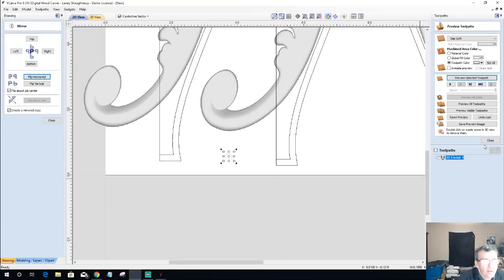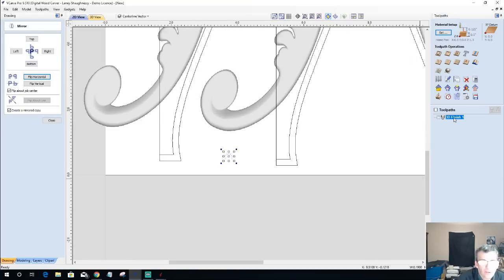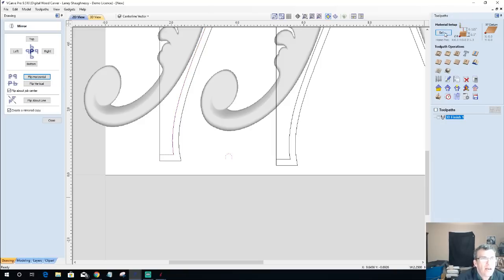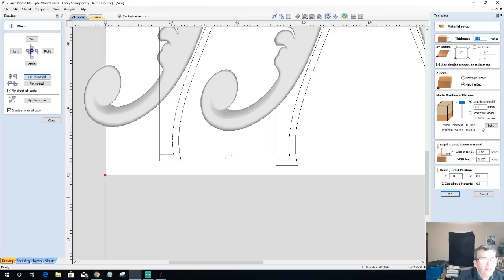And we should now be able to create our molding toolpath. Now in this case, we have to create 4 individual molding toolpaths. So for the first one, we're going to have this part here. Hold down our shift key and select that molding toolpath. Want sharp corners. And we're going to bring this down. Remember, we're bringing it down the thickness of our model, right? So how thick is our model in this part? 0.3382, magic number, 0.3382.